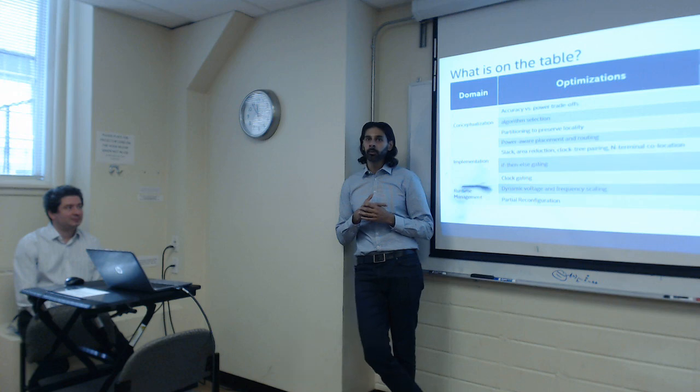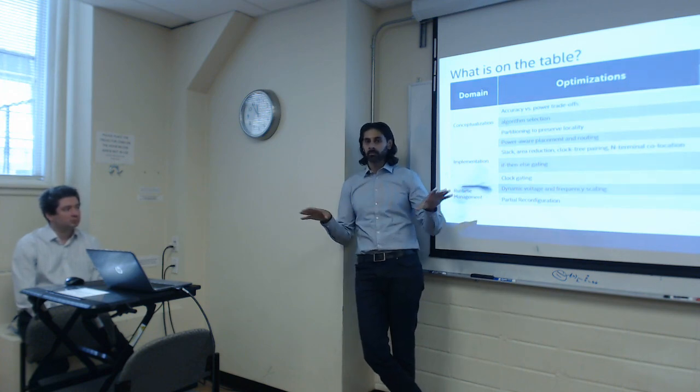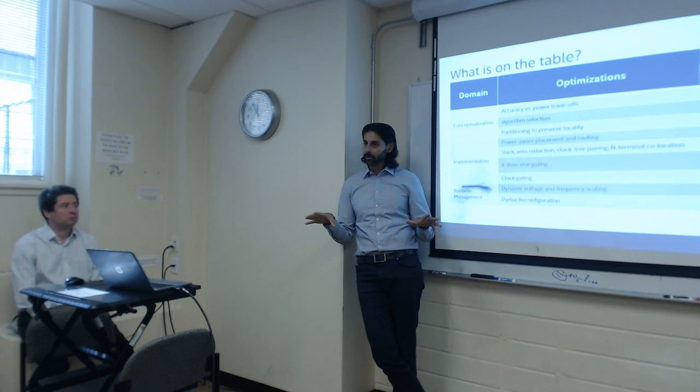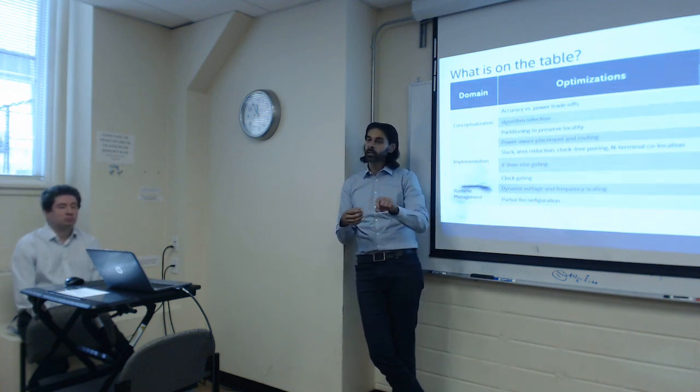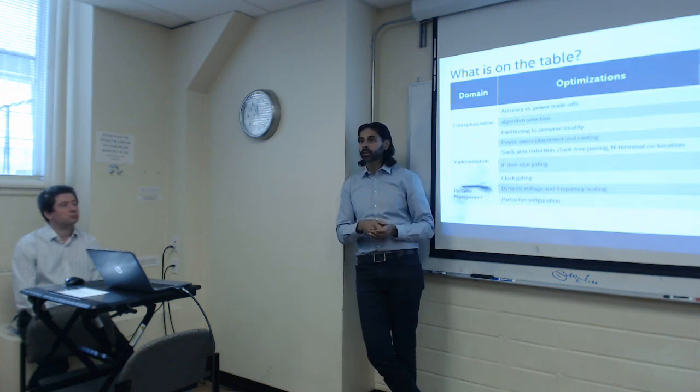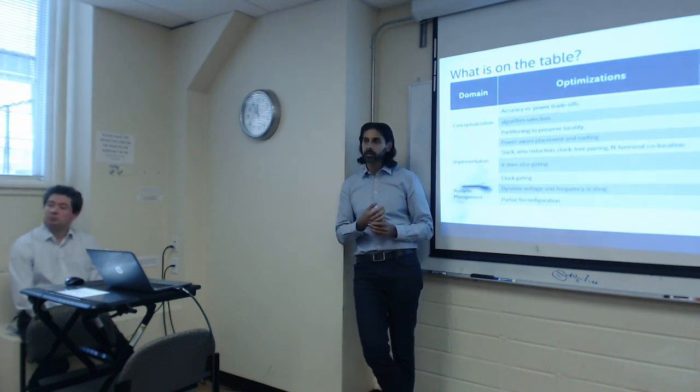Both. What we're trying to help customers do is, one use case would be a customer tells us, please make sure that no point in my package goes above 100 degrees C, and we'll take that as a constraint and ask what is the minimum amount of cooling I need to ensure that happens. That will take into account the 2D models you just described to make sure the worst-case hotspot, given this application, doesn't exceed 100 degrees C. And when you calculate static power, you also take into account the local hotspots to be more accurate. Exactly.